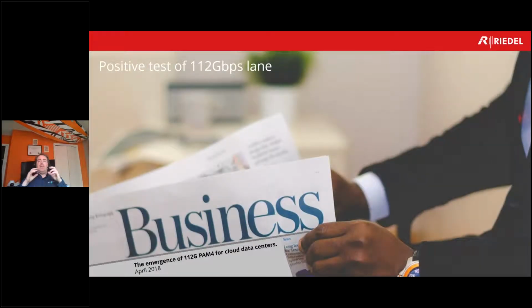So this is just a slide to show you that in 2018, they were able to send 112 gig. So why 112? It's really because when we send the 100 gig payload, we always add scrambling. So this one is probably 66, 64, an encoding to make sure you have enough transitions. So let's think about 100 gig Ethernet. April 2018, they did this. It's 3 years old already, and we're starting to see it.